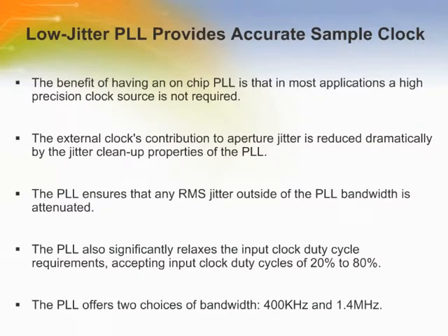A low jitter sampling clock is crucial in all high-speed, high-resolution data conversion systems to realize the full resolution of the ADC. The modulator oversampling clock in the ADC 12EU050 drives the quantizer of the internal sigma delta loop. This clock is provided by an on-chip clock conditioner comprising a PLL and a VCO. The high-performance PLL uses an on-chip LC tune circuit to create a high-Q resonator.